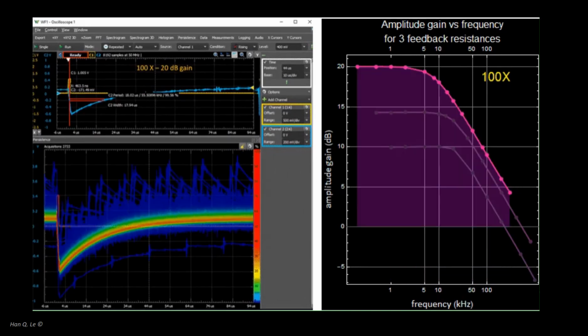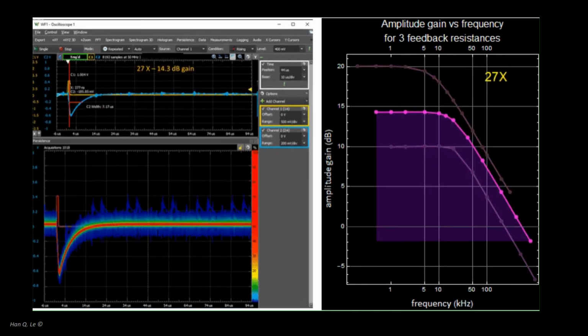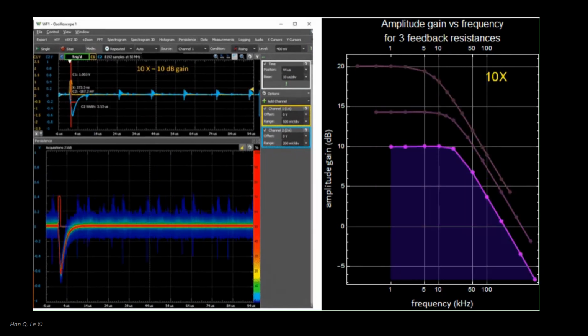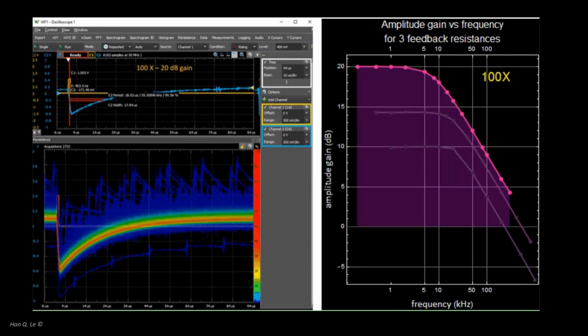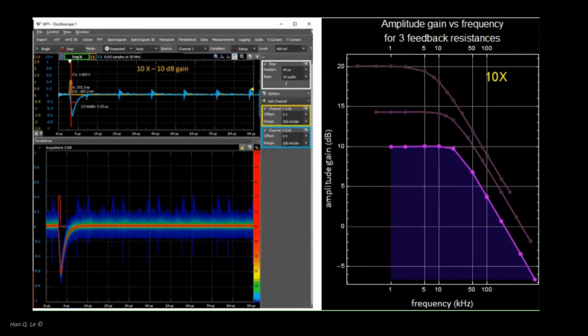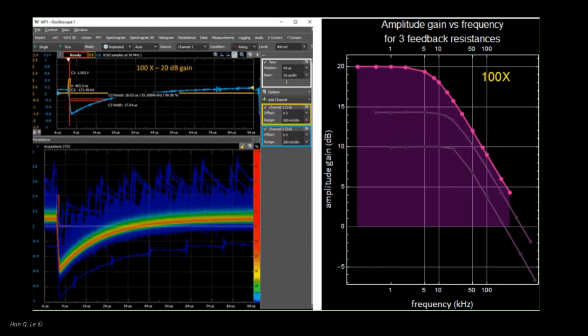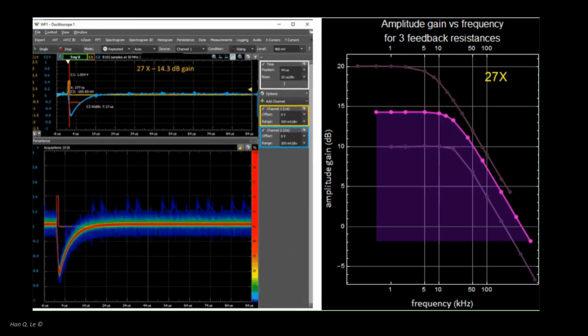In practice, the quickest way to get a rough idea of a system response speed is to do either a step response or impulse response measurement. Frequency response, as shown in A5, takes a bit more work and time, hence, measurements like in A6 or A7 are usually done first to adjust or fine-tune a circuit until a certain response speed meets the requirement. And frequency response can then be done for further modeling.